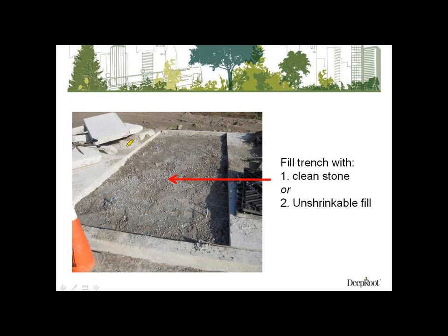Unshrinkable fill is really popular in the cold weather climates, and especially in Canada. They call it U-fill or unshrinkable fill. It's like a flowable concrete. It's a sand light cement mix, so it sets up similar to concrete, but it's still able to be excavated through.